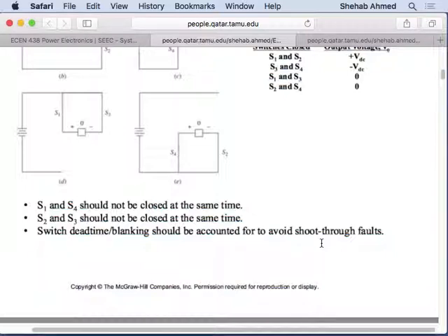If you make it too big, then remember you're going to be losing parts of your duty cycle, right? You're losing parts of your switching period. So if you're losing parts of your switching period, then your ability to control duty cycle is limited. It means that your limit on switching frequency has another consideration as well, this dead time effect that you want to include. So it's not the rise times and fall times of the switches only now. It's also the amount of dead time you need to insert, right?